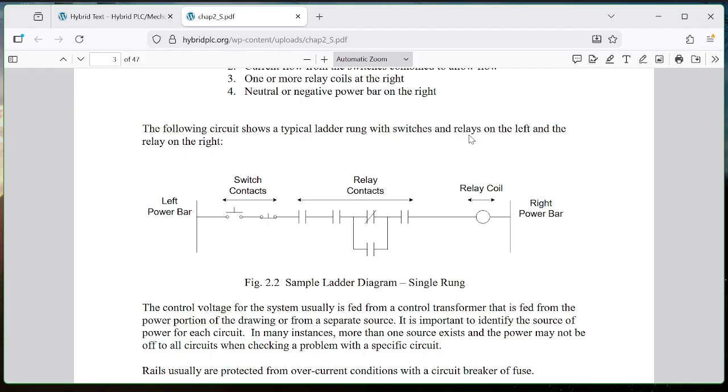V equals L di over dt. Voltage equals L, the derivative of i over the derivative of t, all right? If i immediately goes to zero, what happens to voltage? What's the derivative of a step? Infinity. Nobody gets an infinite voltage. So you have to have a little bit of arcing and sparking because the current jumps across the contacts as it's opening. Okay? That's why they wear out. That's why you get so many operations on them, but you don't get an infinite number.